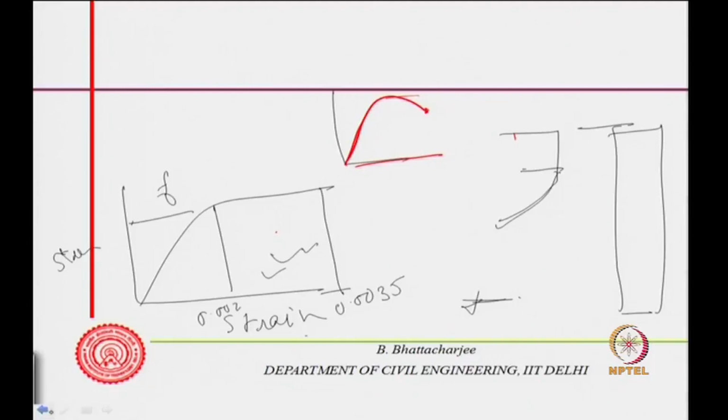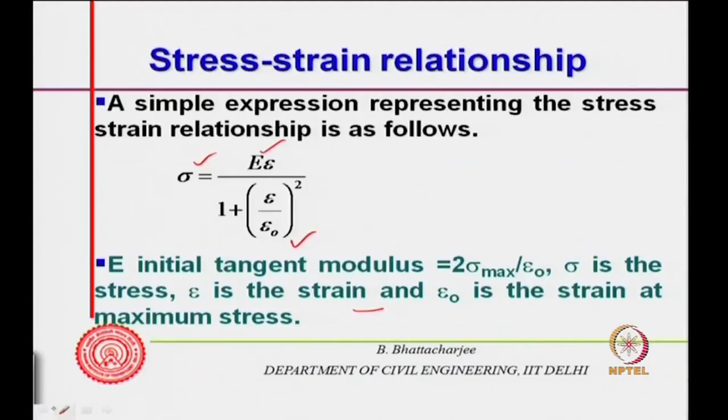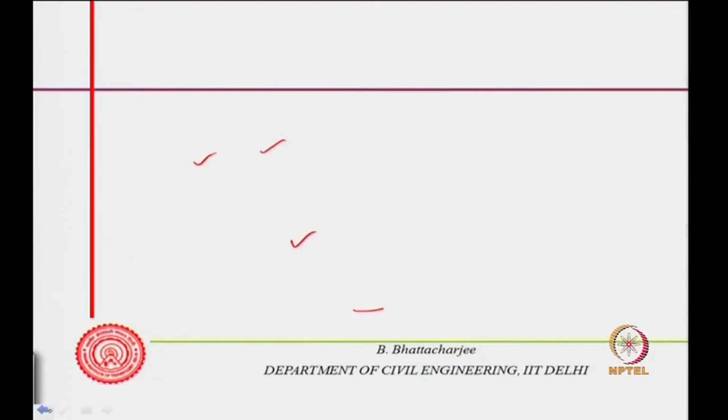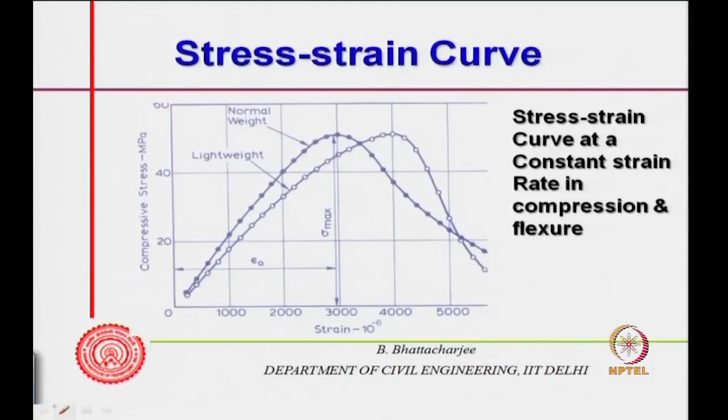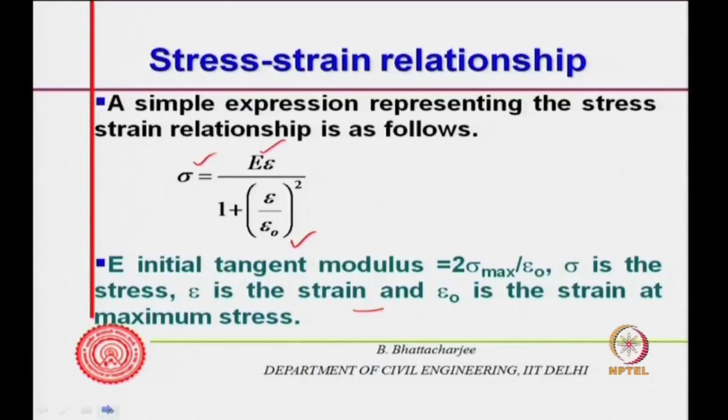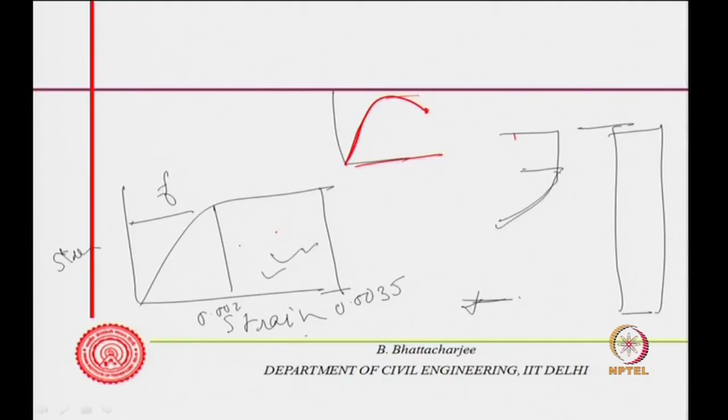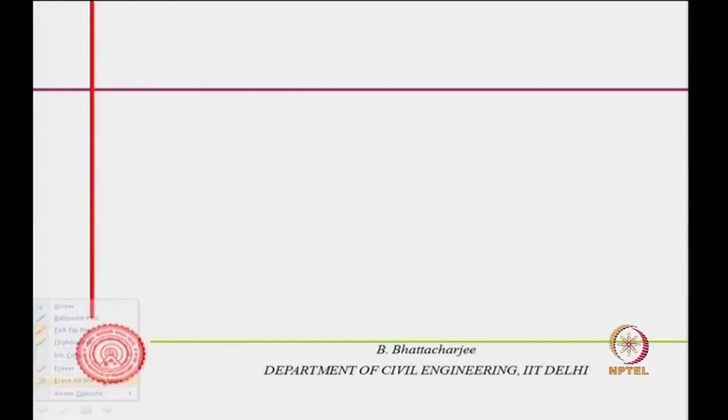So, the measured stress strain curve, the actual stress strain curve observed as we have seen, is idealized into this sort of straight line curve, and of course, certain factors are applied to bring down the load as well, which I am not discussing at the moment. So, the importance of the stress strain curve is here, because in flexural design you have to use this. The idealized curve is something of this kind, arrived from this real behavior. So, that is the importance of the stress strain curve.